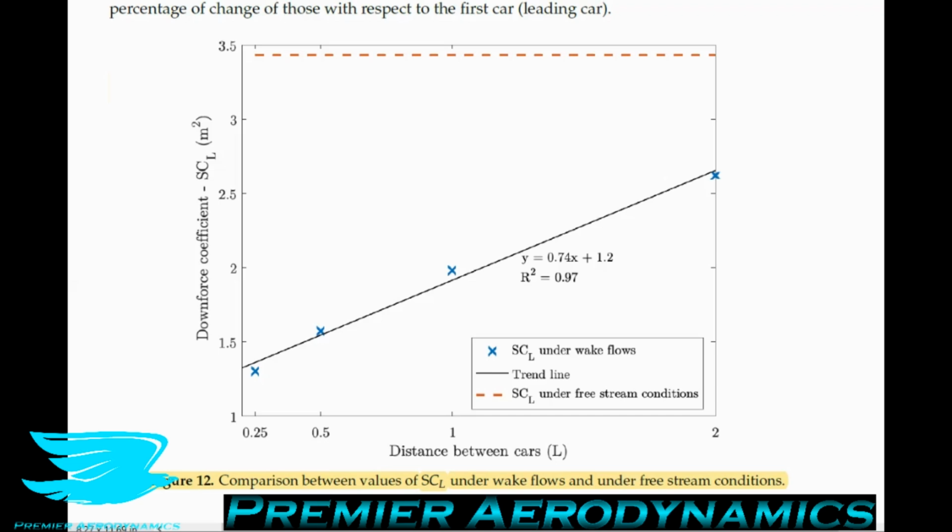So it can be concluded that the wake from the upstream car is very detrimental to the downstream car's lift production, or downstream downforce production, I should say. This means that as the downstream car approaches the upstream car, the speed at which it can corner drops dramatically because it loses downforce. So you lose friction, which means you can't go around the corners nearly as fast. And that makes it harder and harder for it to overtake the upstream car in the corners.